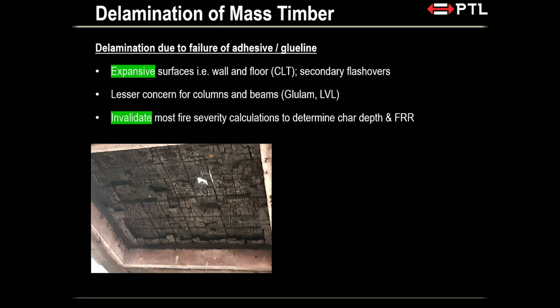All right, look, I'm going to move on to the delamination. Okay, why do we worry about the delamination? Because right from the beginning, I told you it's a system, and there are different types of adhesive. If the adhesive selected for that particular mass timber supplier is non-fire rated adhesive, then once the heat gets onto the glue line, it will start delaminating. Now you wonder why you worry about the delamination. Is it such a big deal?